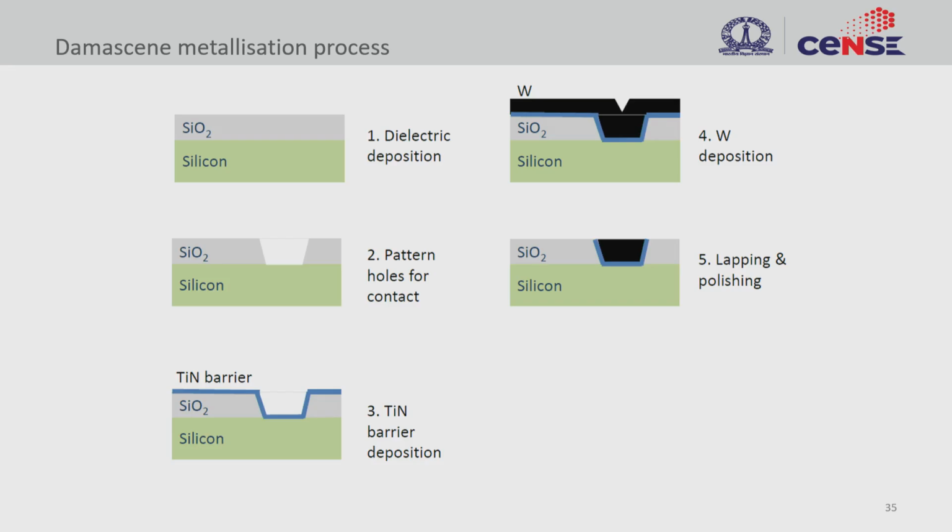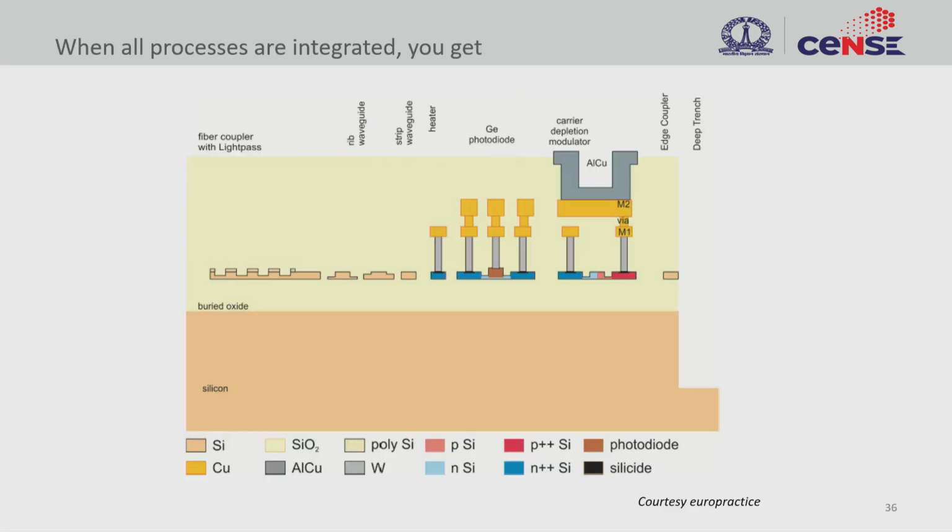So finally, metallization. Once you have this flat oxide, we will follow the lithography and etching steps in order to make these trenches, and these trenches can be filled with the metal deposition that we saw earlier, and then you do the CMP, right? When you repeat this process, you can build complex structures, as we saw earlier, that should result in the desired cross section that you want.